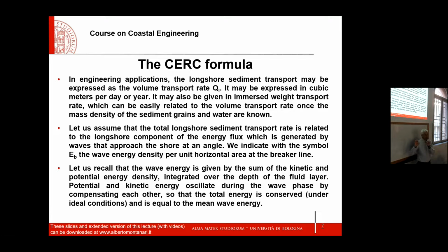Now, the CERC formula deals only with the longshore sediment transport. Let's forget about cross-shore for now. So I am interested in this component here. Of course, the longshore component is given by, I can say that the wave direction is the longer side of the triangle, which is a right triangle. So the longshore component is given by the energy of the wave along the wave direction times the cosine of this angle alpha.